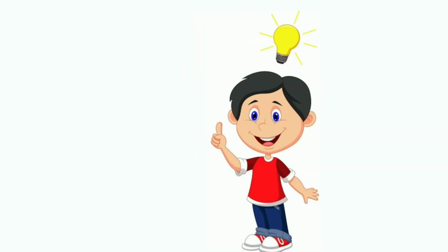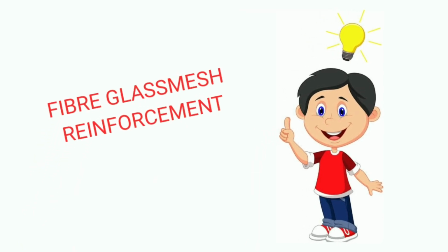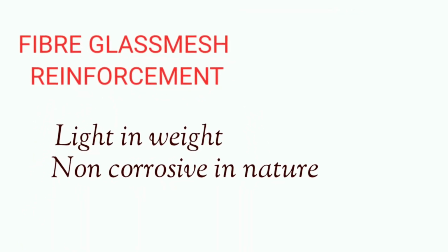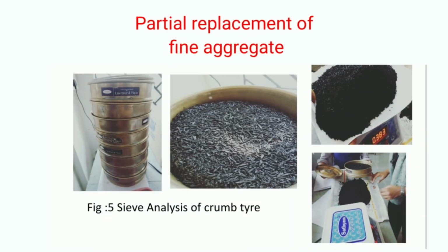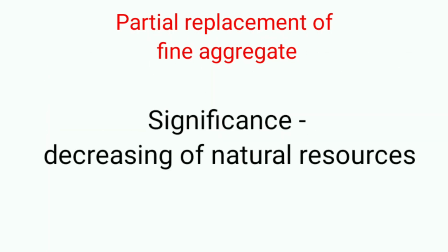So we came forward with an idea of fiberglass mesh reinforcement, which is light in weight and at the same time provides strength and is non-corrosive in nature. We also provide partial replacement of fine aggregate, as natural resources are depleting day by day and there is a need for minimizing the use of natural resources.